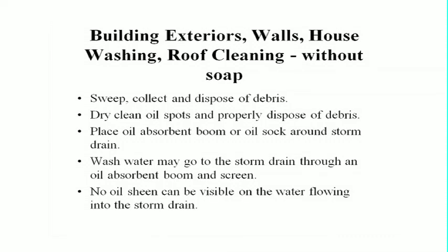Building exteriors, walls, house washing, roof cleaning without soap. Sweep and collect the debris. Dry clean oil spots and properly dispose of the debris. Place an oil absorbent boom or sock around the storm drain. Wastewater may go to the storm drain through an oil absorbent boom and screen.